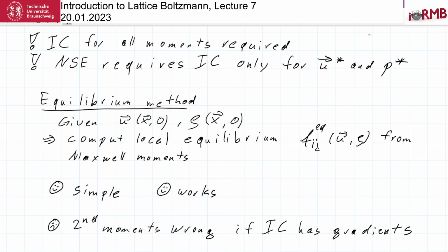Depending on your objective, for example, in the homework your objective is to compute the lift and the drag. So what you would usually do is run the simulation for a number of time steps, then you see that now we get to a point where nothing changes anymore, so we cut off the initial part and do the averaging over the rest, and we don't care about the initial condition.